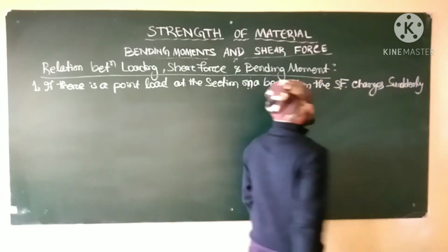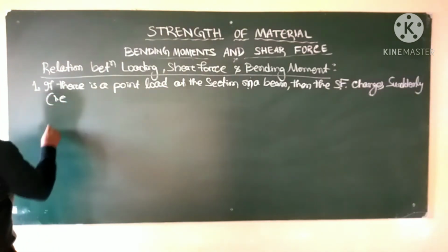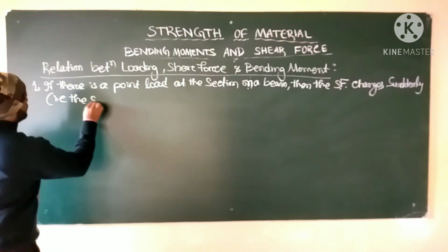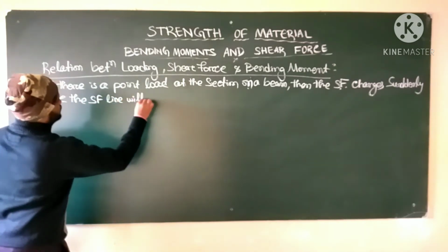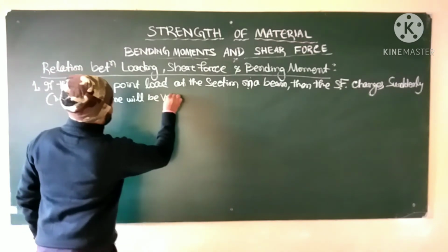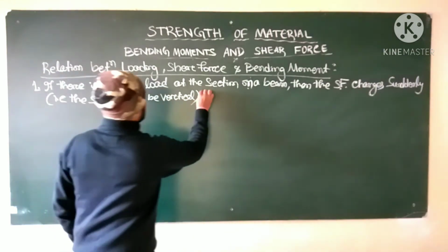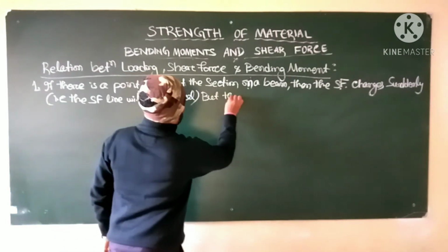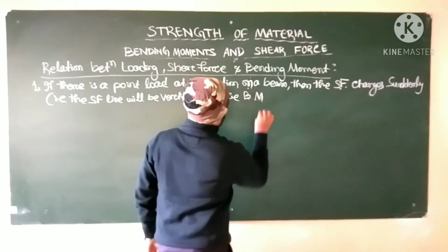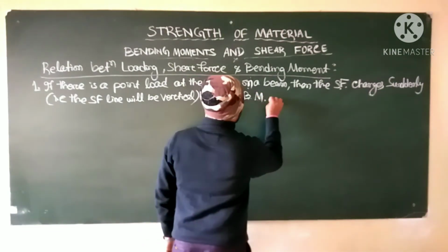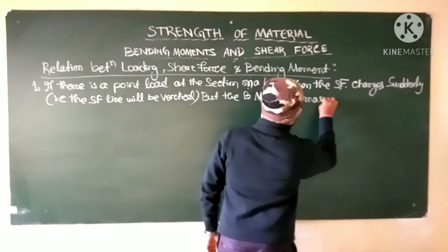Then the shear force changes suddenly, that is, the shear force line will be vertical. But the bending moment, or BM, line remains the same.